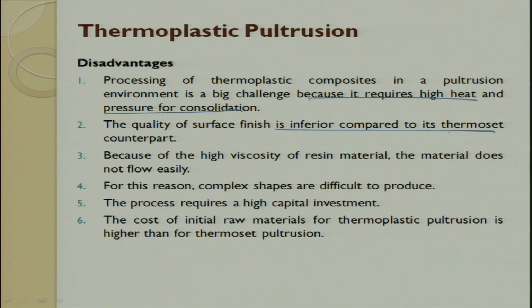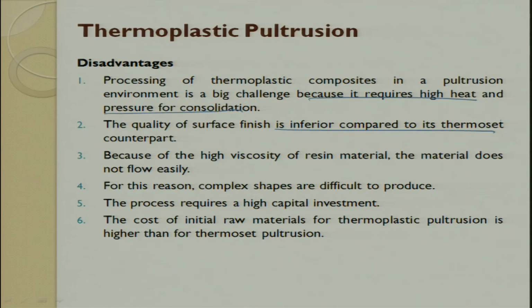So, that is what a lot of research is going on, and since it is recyclable, today we make a lot of reinforcing structures in the automobile and aerospace industry, where metal alloys used are now replaced by thermoplastic pull-through shafts, in which the fiber takes the load, and this gives a huge breakthrough in weight. So, this process is picking up, but the only problem is it has very poor surface finish, which is what a lot of research is going on.